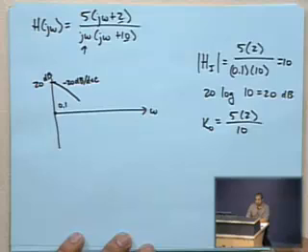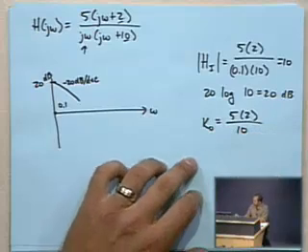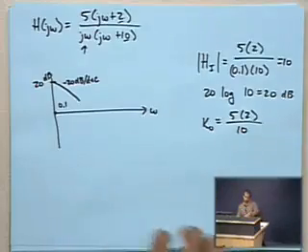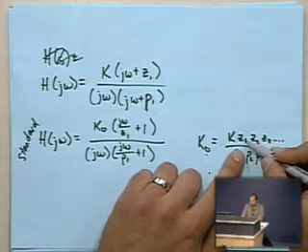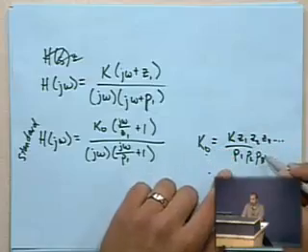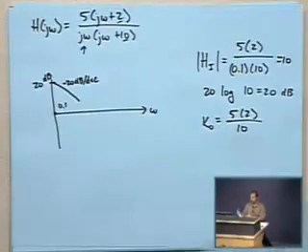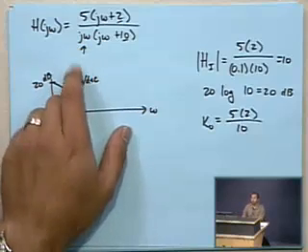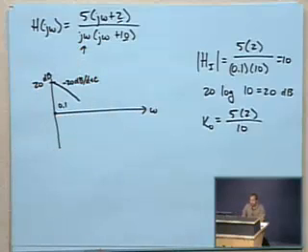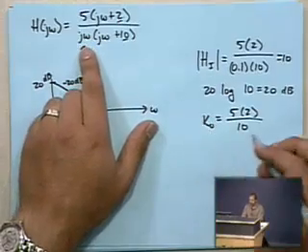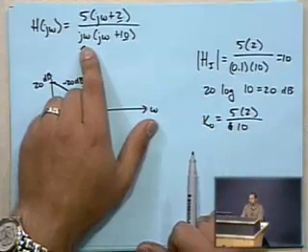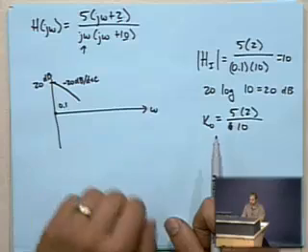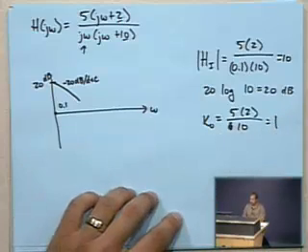Are you keeping up with me so far? Okay. Remember our basic form for k0: we took the original value of k, multiplied it by all of the various zero values, and then divided it by the appropriate pole values. So what about the pole at the origin? No, because it would be problematic if we put a 0 down here. So we ignore that one in terms of calculating what k0 is. And so that means that k0 is 1.